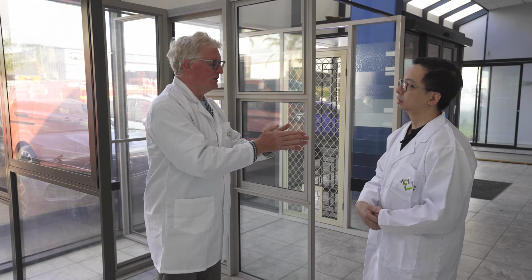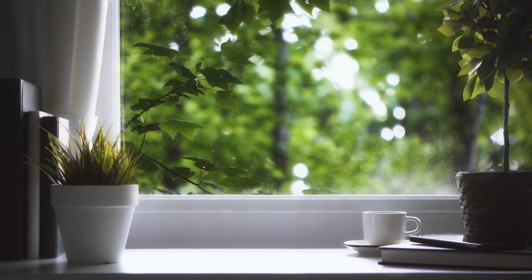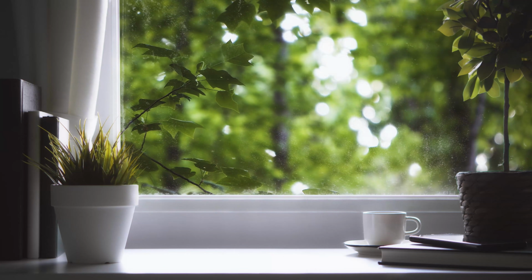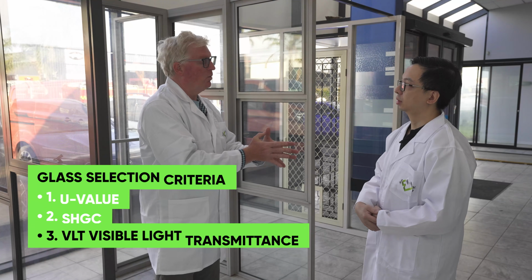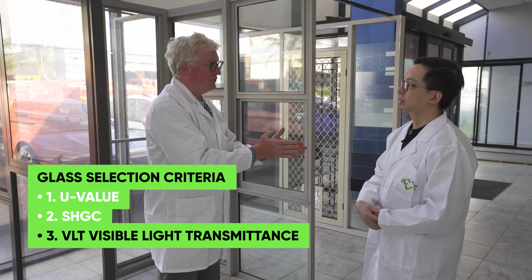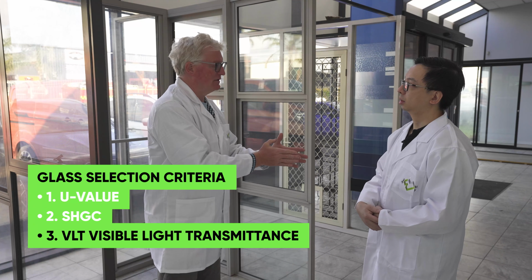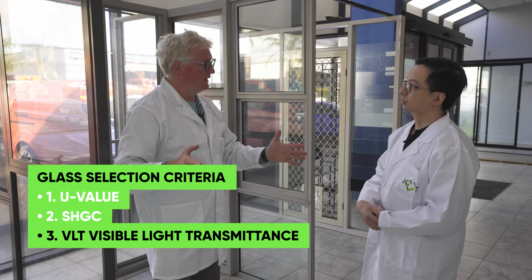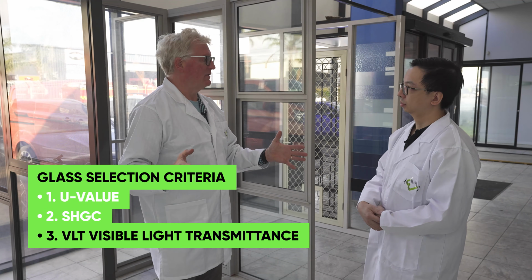And what's important to realize is that there's a portion of the solar spectrum that gives us what we know as visible light. And it's important in many glazing systems to look at what the visible light transmittance of a glazing system might be versus the solar heat gain that is being transmitted or admitted through the system.